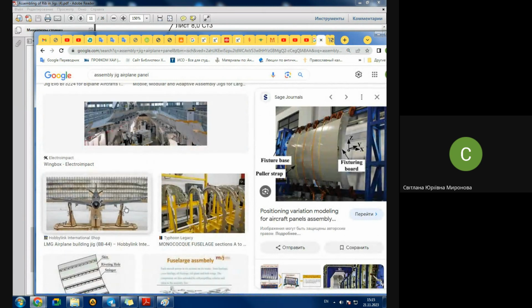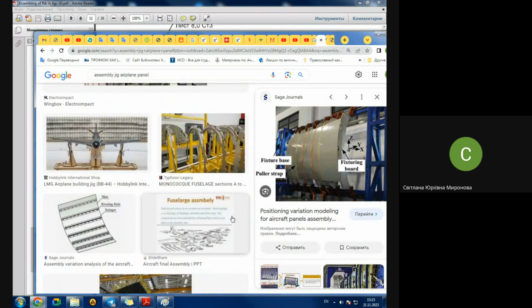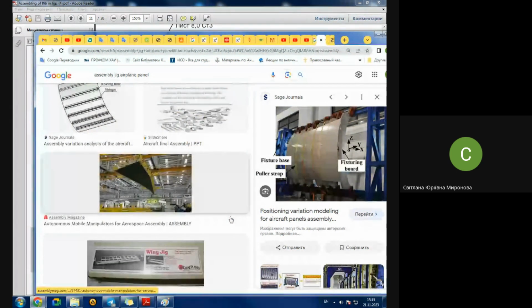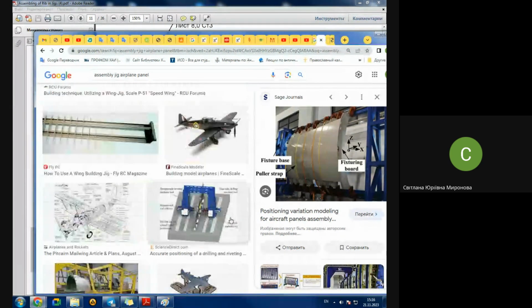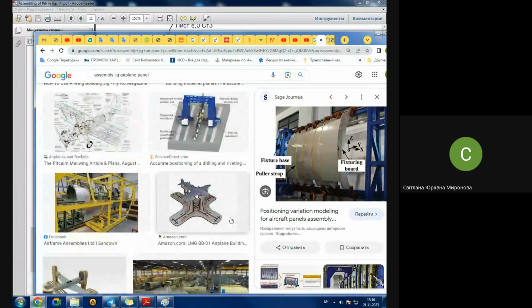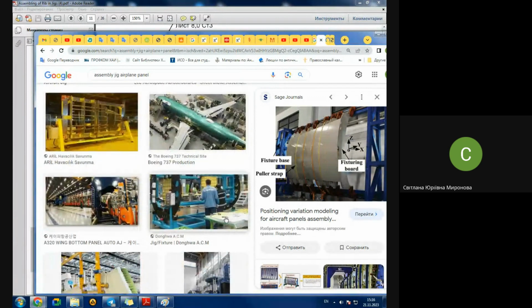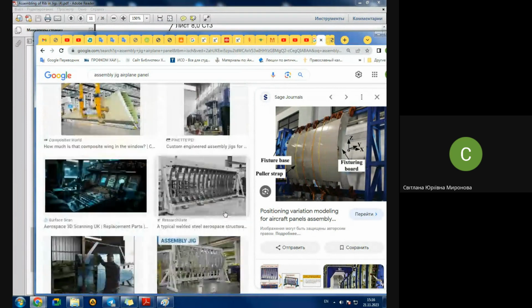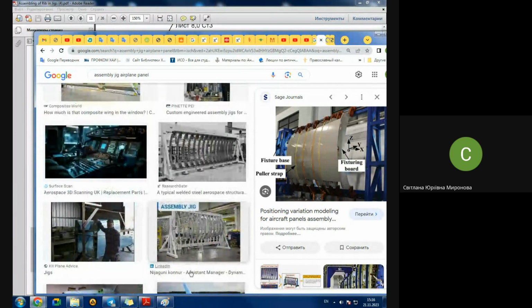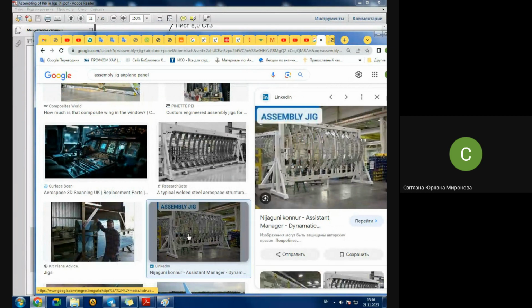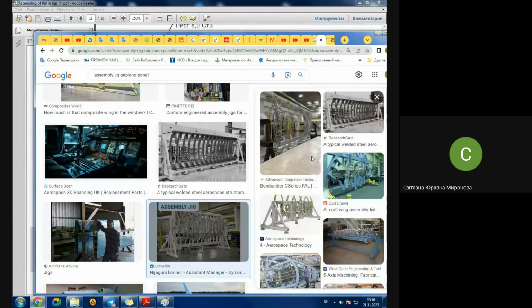And when you need to join something with a bracket, for strength and accuracy, instead of a simple portion of this cement, you need at least a couple of screws for each bracket and at least a couple of pins. And what does it mean? A couple of pins, a couple of screws, it's like you're drilling the hole and next countersinking the hole and next reaming, making thread.